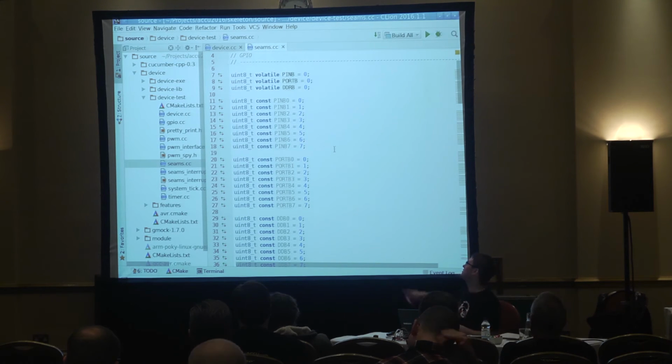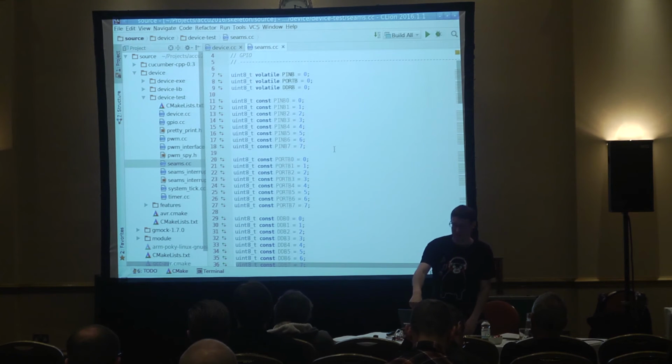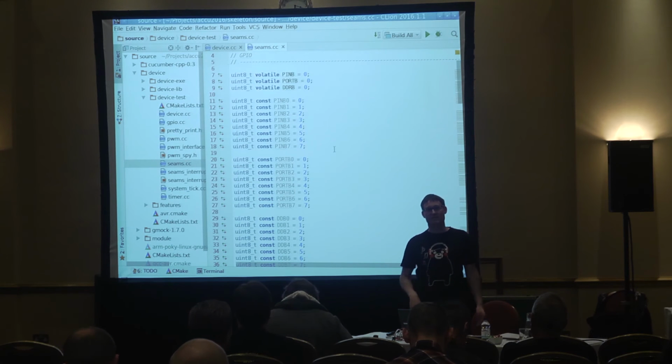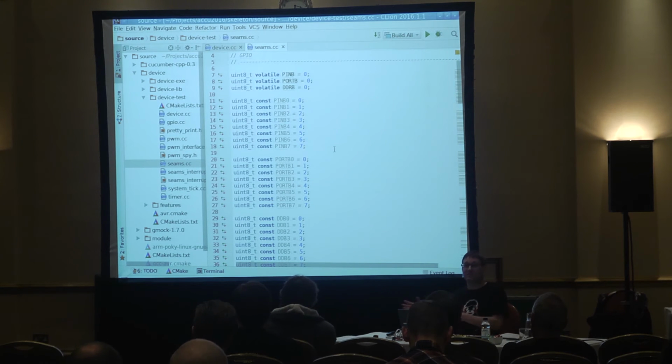On the target, normally for the AVR, I think it's a nasty macro that then ends up with a reference or a dereferenced pointer, or something else itself, I don't remember. You include this from the toolchain for this device. You include the header file, and you get them. And in the test, I don't really include the device header files. I have like a test stub of that.